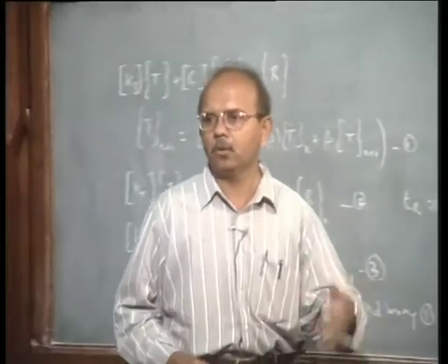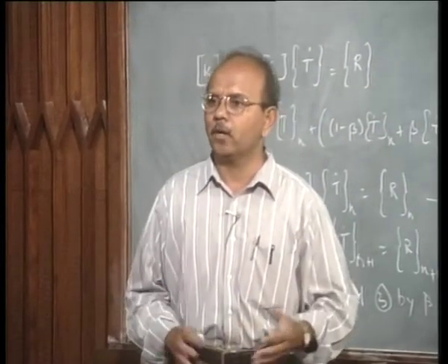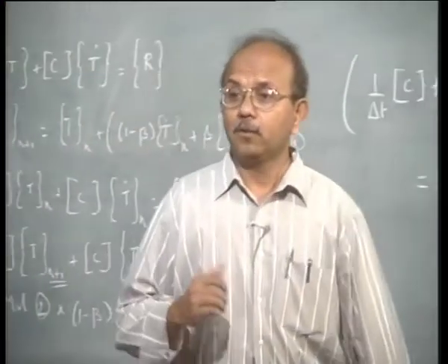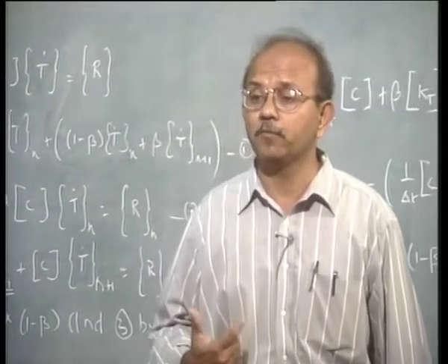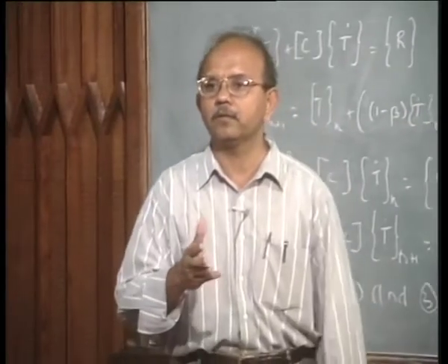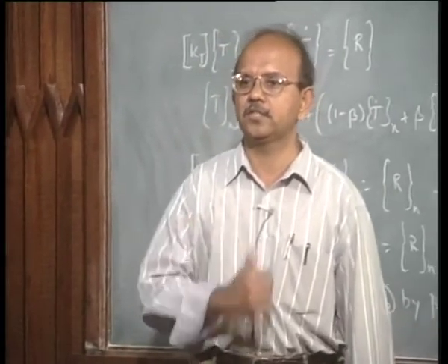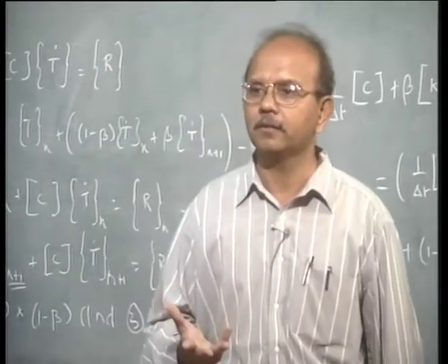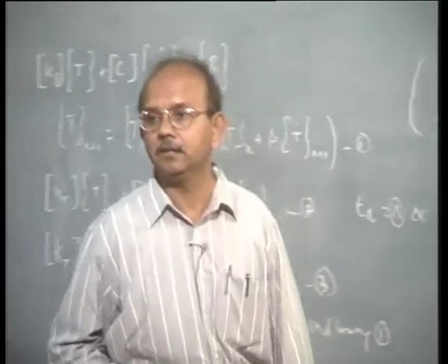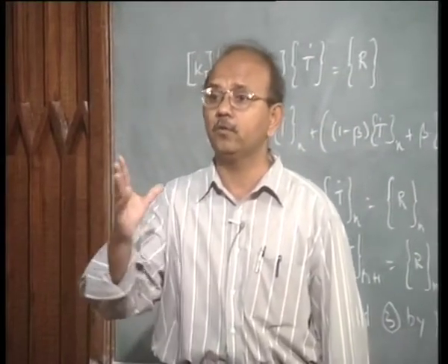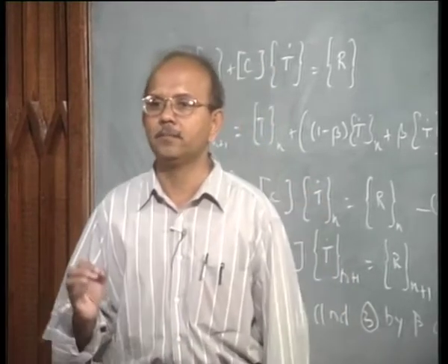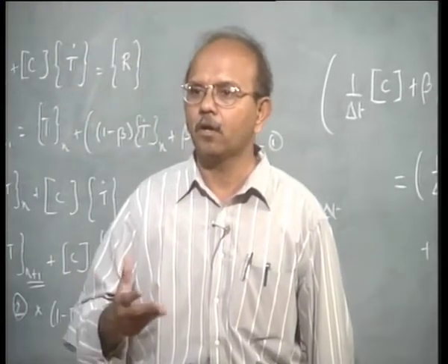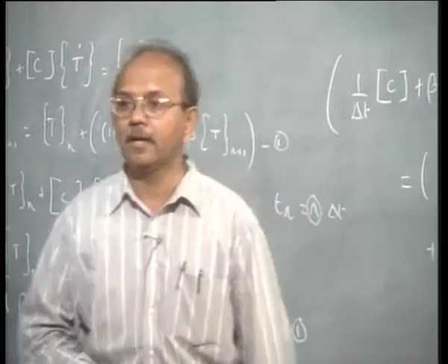Yeah, K, rho, Cp and so on, all these things are also a function of temperature. Not only that, when we solve mechanics problems, especially with welding distortions, residual stresses and so on, what is involved there? Sigma y, yield strength, and other mechanical properties, maybe E. These are also functions of temperature. So it is important to realize that whatever we are looking for or seeing are all functions of temperature. Let us go back and have a look at that slide again.